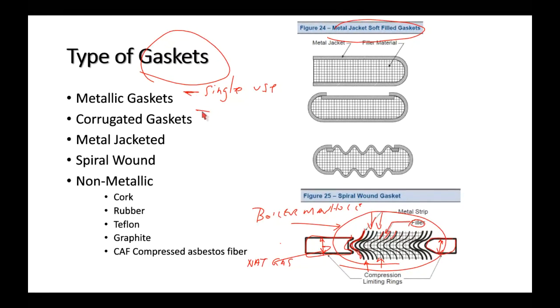What I used to do when I was a boiler inspector is I used to go into plants and I'd see the manhole gaskets and handhole gaskets kind of like piled up on the corner, and I could tell that they were used because they're kind of hard and maybe starting to get a little bit brittle, maybe they're cracked just a tiny little bit, but they were definitely compressed. They were used at least once.